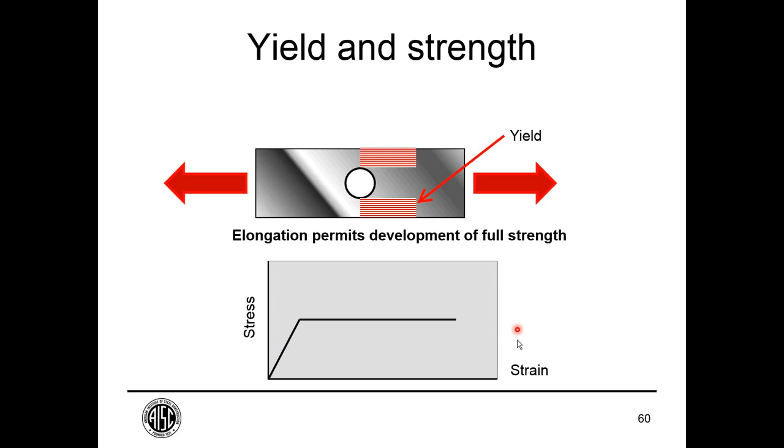Now, if we have a ductile material, like that steel that I just showed you, we have peak strain in the same location, and that's way out here. But our strain may be lower at the edge of this material, but our stress isn't necessarily proportionally lower.